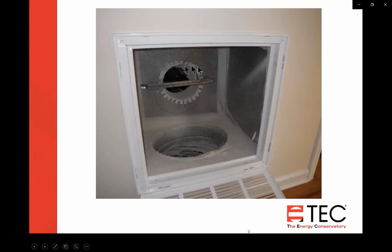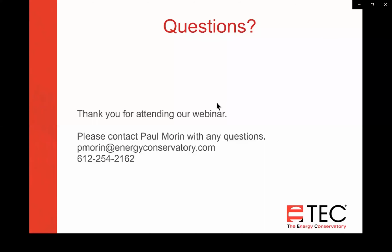For bigger cracks and bigger leaks, you want to use some mesh tape and put that on first, and then goop over it with the mastic. So they missed that one, and that one was still leaking, and that would show up in a smoke test.